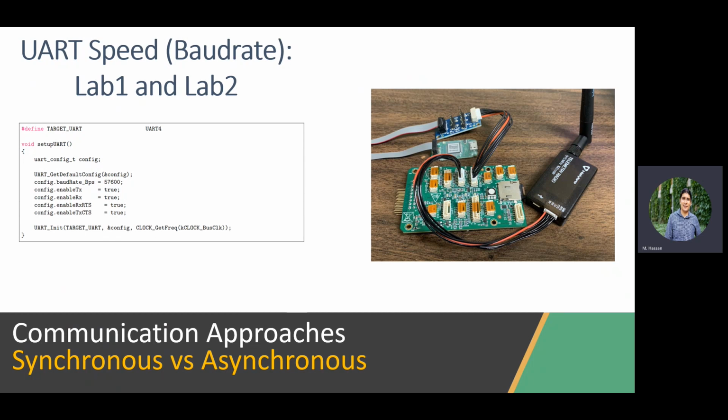The one that is attached to the desktop is a USB connection, which means you deal with it in a UART fashion. So through the command, you will set up your baud rate. The data transmitted will be sent to the wireless transmitter that is attached to the USB of the desktop. Then the wireless transmitter will send it to the wireless receiver, and then the wireless receiver will send it through UART to the actual FMU, right? So we're using UART on both sides, but the connection in between is wireless.